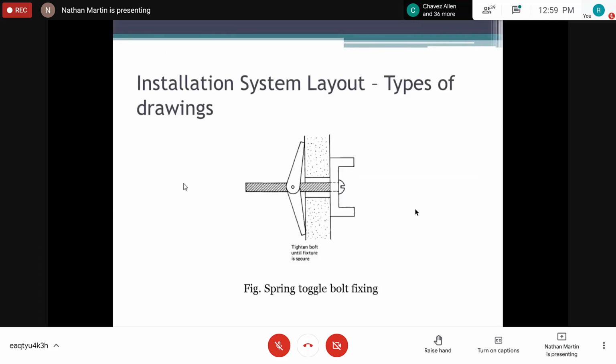Now, this is really an example of a freehand diagram. It's not a hand sketch, but it should be a hand sketch. It does show you how you will mount a device to a particular hollow wall. So it's basically how a spring toggle clamp will work when used on drywall or wood. Here, this sectional installation is hollow. You bore a hole, you push through it, and then the spring tension will release and put the clamp into place.